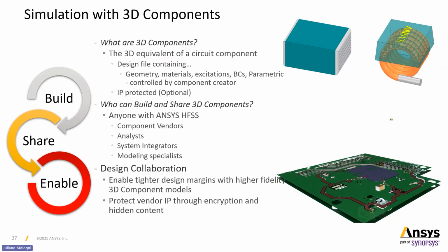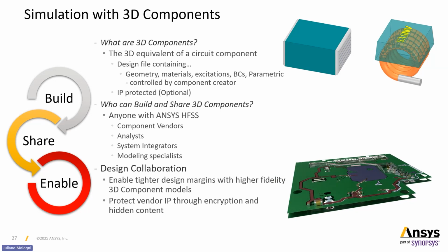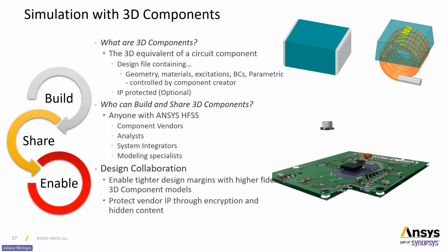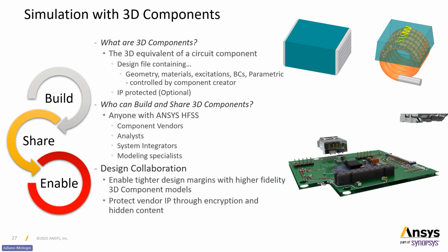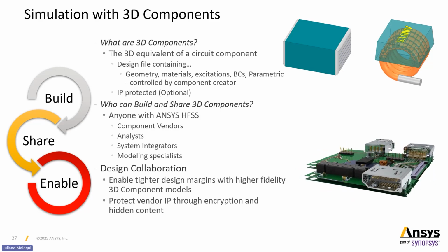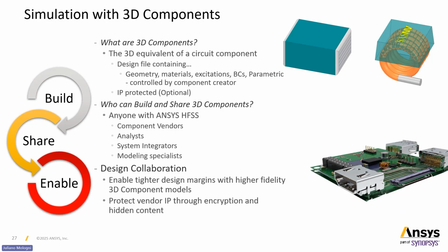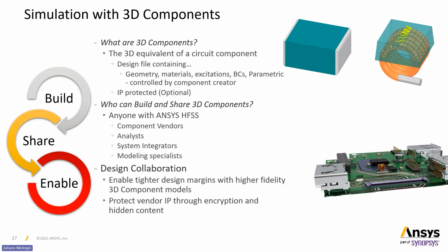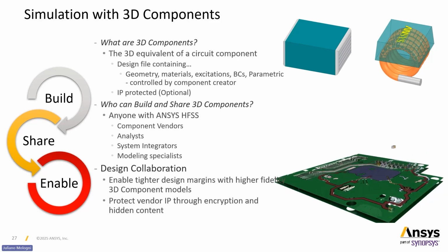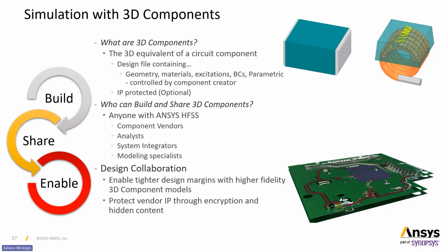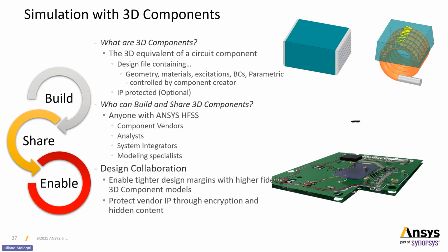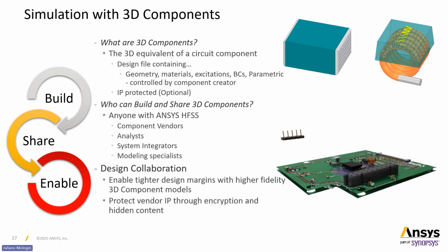The reason I'm bringing HFSS in here is that we have a patent on this, and we have introduced to the market the concept called encrypted 3D components. What you're seeing here is a PCB made of 3D components: connectors, cables, capacitors. The problem we saw in the industry is that someone designing a PCB is not designing the connector. They're buying it from a vendor, and that vendor doesn't want to supply the HFSS model because it's their IP. So we came up with the idea of encrypted 3D components.